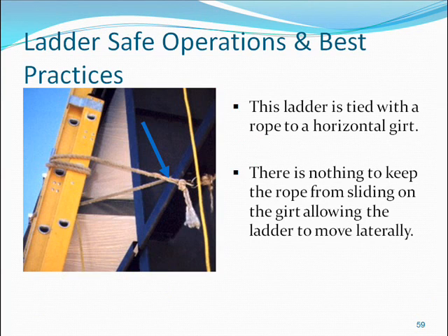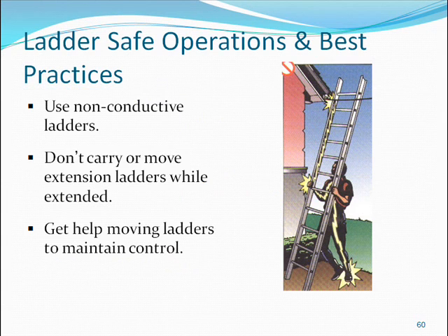This ladder is tied with a rope to a horizontal grid. There is nothing to keep the rope from sliding on the grid, allowing the ladder to move laterally. Use non-conductive ladders. Do not carry or move extension ladders while extended. Get help moving ladders to maintain control.